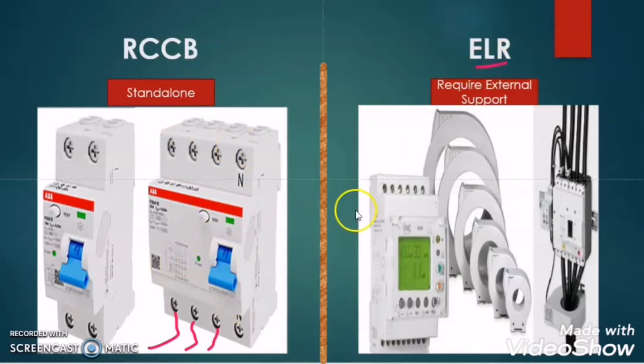But with the ELR, when an earth leakage fault happens at the load side, the ELR will not trip until and unless it gets a signal from its supportive device, that is the CBCT, core balance current transformer. So the ELR needs an external device to support it to trip the circuit, whereas the RCCB alone senses the fault and trips itself.